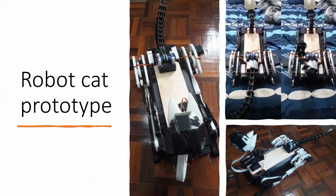So moving onwards, we have the pictures of the robot prototype. As you can see here, we have the whole body. We have the head, which is connected to a Raspberry Pi camera. The intelligent system for image processing and face recognition is run using a Raspberry Pi 4, and the motor functions are connected to an Arduino system which runs them in a serial interface with the Raspberry Pi, and the IoT capable functions of the battery health and GPS are connected to a Node MCU ESP32 controller board.